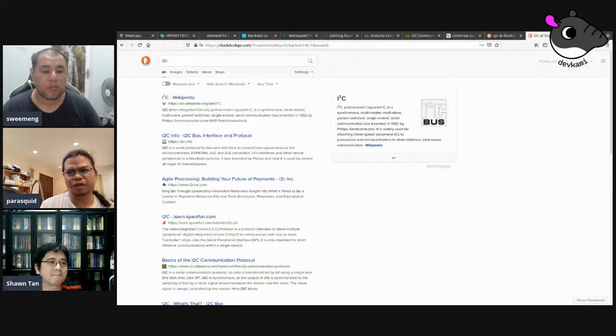Are you restricted to that 100 kilobits because you have a clock line, right? So you can basically control the clock. Yeah, you can stretch it, and you can even go slower if you need not more bandwidth, but more data integrity. Like you need to keep it low for longer and keep it high for longer, just so that it actually gets through. Yeah, clock stretching.